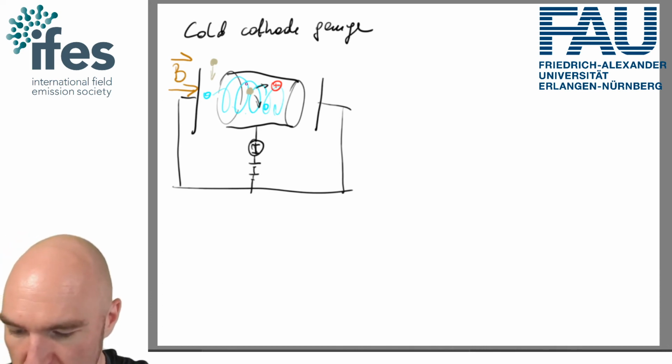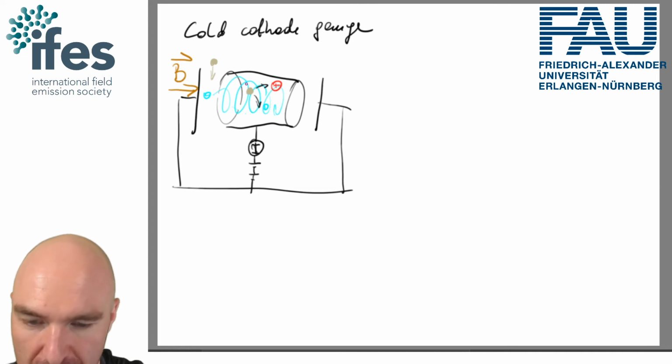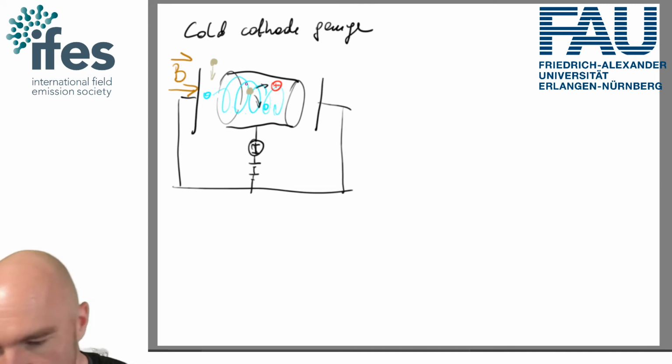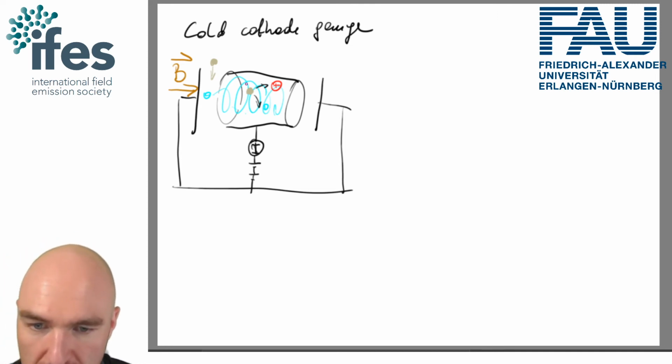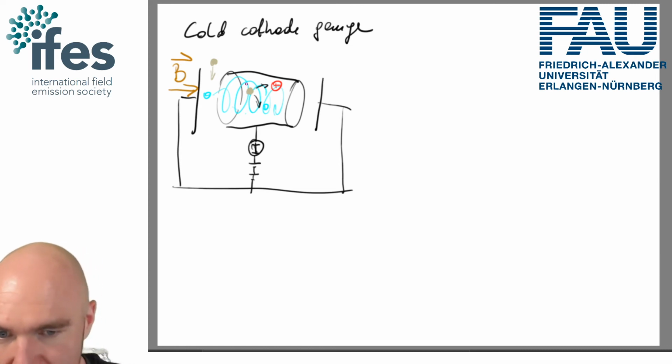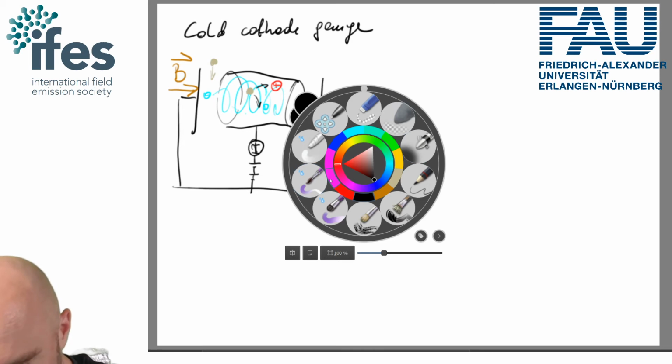The thing is, of course, in this case that the ionization cross-section and the ionization potential makes quite a difference. So the harder something is to ionize, the more the pressure reading will change with the gas, so that you will get a gas dependency.